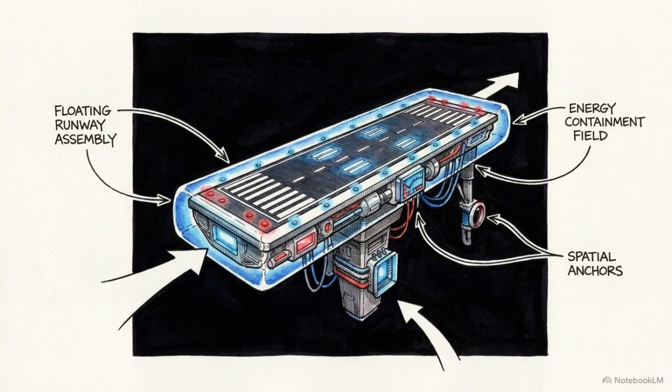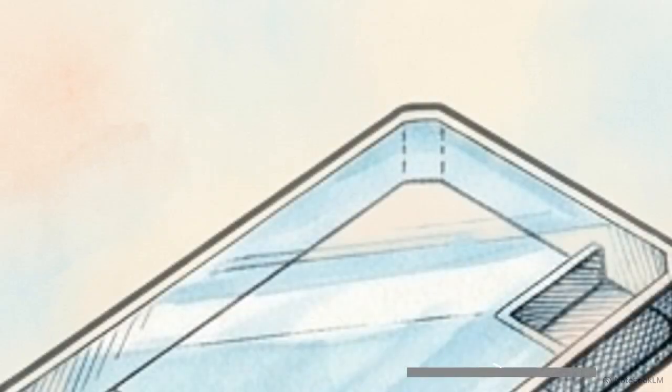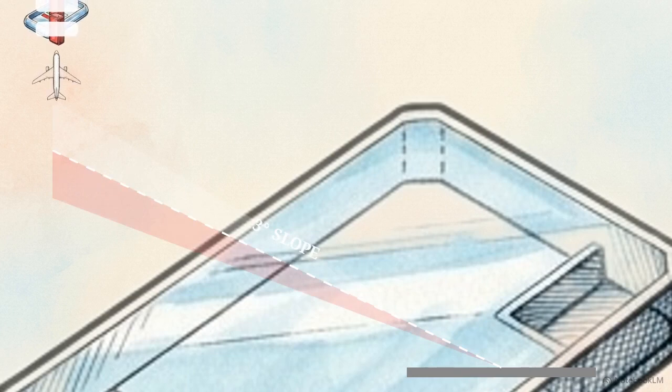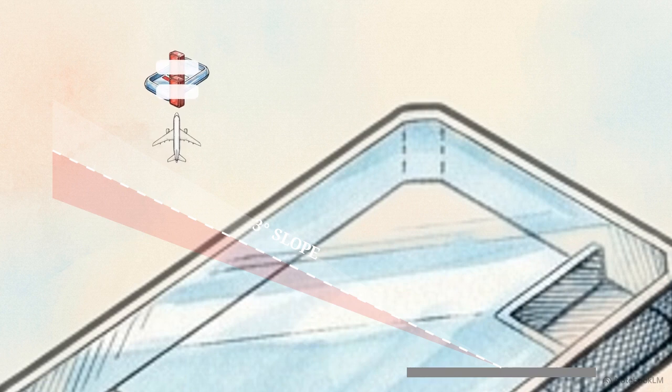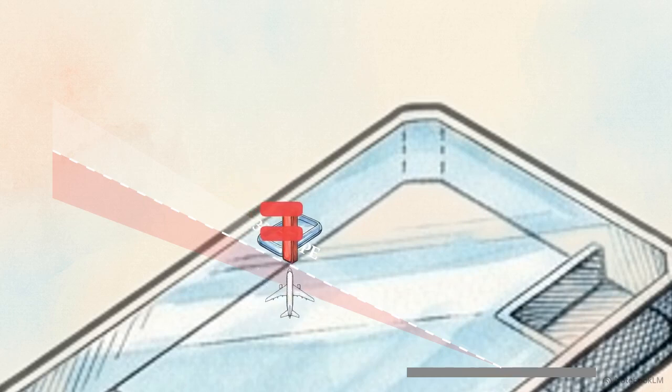Aligning with the horizontal runway is only half the equation. In total darkness over an unlit landscape, a pilot has zero visual reference to judge their vertical descent angle. The Visual Approach Slope Indicator, or VASI, utilizes engineered optical projectors to emit discrete visual corridors upward into the approach path, typically set at a 3-degree slope. As the aircraft moves vertically through the airspace, the lenses filter the light based on the plane's exact physical altitude.